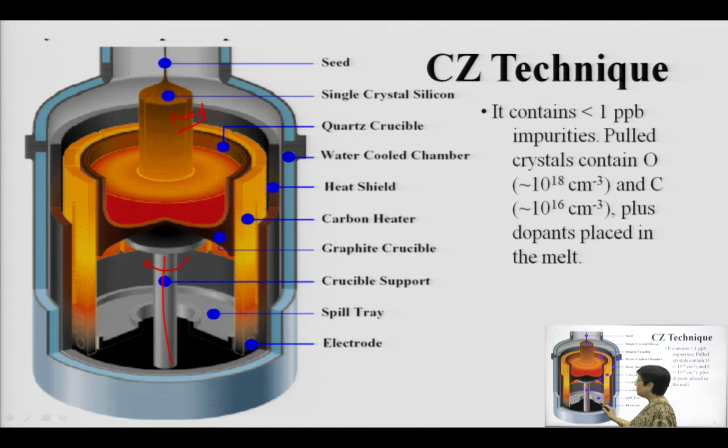This has to be stable, and you have uniform heating throughout the molten silicon, because whatever the diameter of the crystal, throughout that surface you should have uniform heating within the molten silicon, so that the deposition is proper and the rate at which the deposition is happening is precisely controlled.